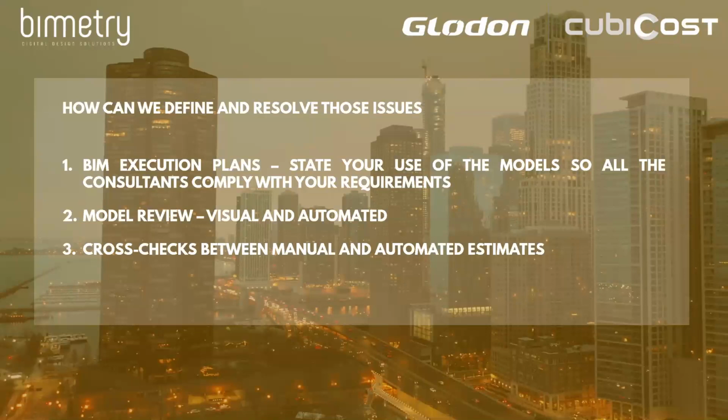And another, let's say, more manual way, of course, is just to choose a portion of the model, do manual cost estimation and quantities, and then do automated estimates and see how it is in terms of overlapping, or is it too different. If you get very different figures, you immediately get a red flag saying maybe some geometry hasn't been modeled in native Revit, it's an import, so that's why it's not picked up. Some geometry might be just 2D lines, or you might have a lot of overlapping geometries. Usually it doesn't take long to realize what is the state of the models.